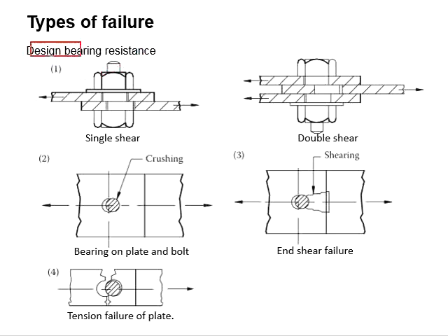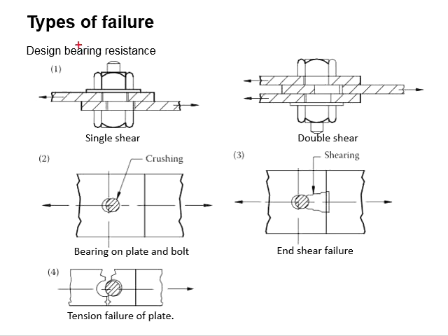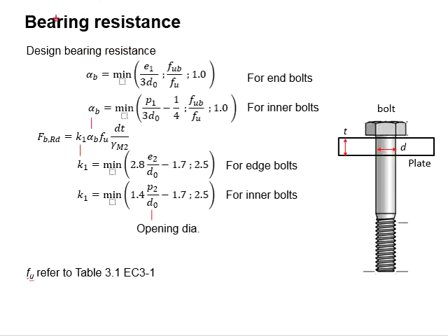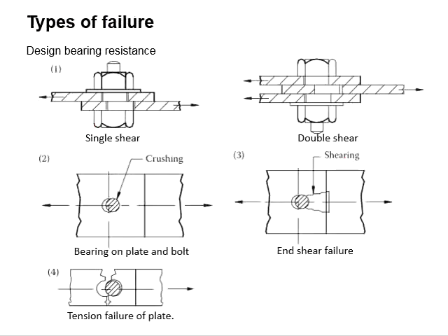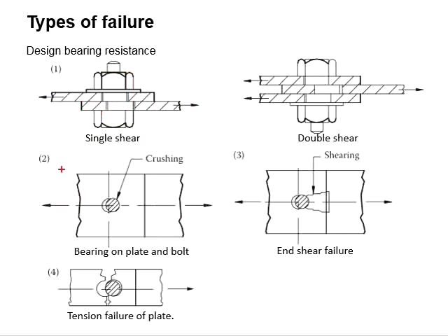Next, we need to look into the setup of the connections. The resistance of the connections due to the bolt will be governed by the number of shear planes. Next, we look into the bearing resistance of the steel plate. For a tensile splice being subjected to the tensile load, one of the plates is moving to one side while another is moving to the other side.